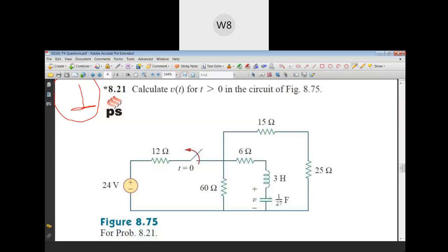And there will be resulting current which will flow through the inductor that will result in magnetic flux, or in other words, you can see that energy in the form of magnetic field. So here in this system, energy initially in the form of electric field stored in the capacitor will start getting converted into the energy in the form of magnetic field in the inductor. And then finally the complete energy transfer will take place in the form of magnetic field inside the inductor. The net charge or the net electric field in the capacitor is going to be 0. So you can say that the initial potential energy has got converted to 0, and in the form of kinetic energy. So now we have only kinetic energy,